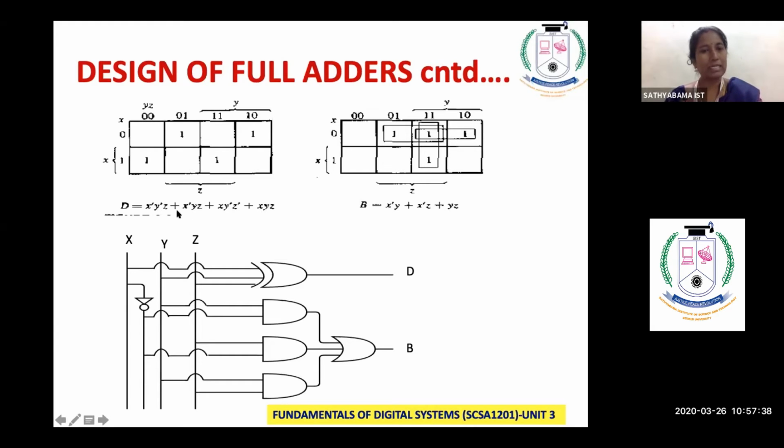It's okay to memorize that the difference expression is an XOR gate for a full subtractor. Sorry, here I wrote full adder; it is full subtractor. So here is the difference expression with the help of an XOR gate. And here you are having x dash. This is x, so how to convert that to x dash? With the help of a NOT gate. So I have connected it with a NOT gate, and then connected it to AND gates, and finally we have borrow.